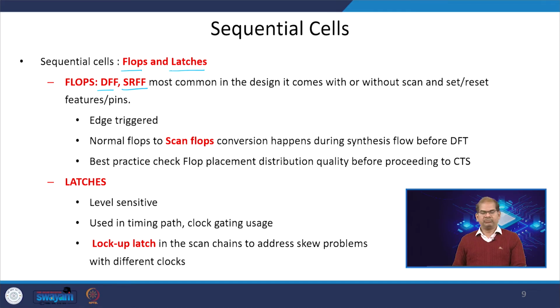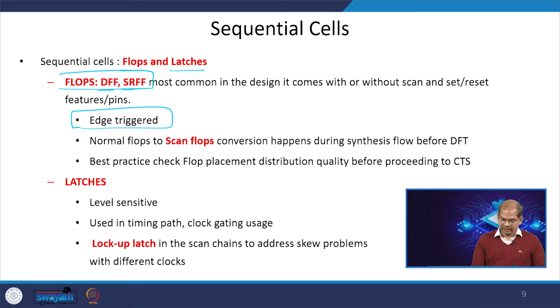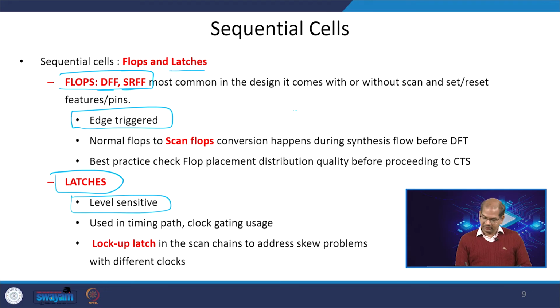Before going to the flavors, your flip flops are edge triggered and latches are level sensitive. In the flip flop case, your signal can be captured either on the positive edge if it is positive edge triggered, or sampled on the negative edge if it is a negative edge triggered flip flop.